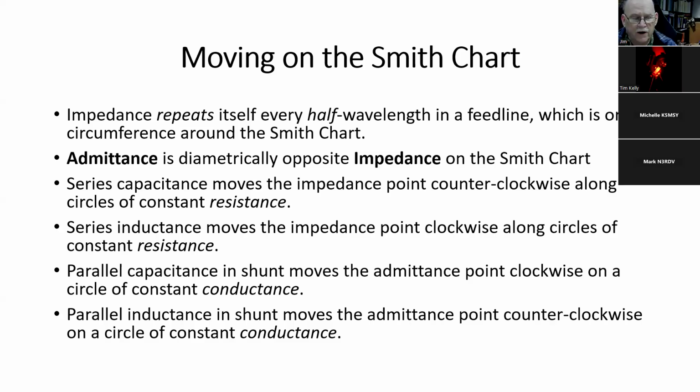Jim, yeah, go ahead. I tried to message you, but you didn't hear me or see it. On the first bullet point, impedance repeats itself every half wavelength on a feed line. Is that affected at all by the velocity factor of the feed line? Yes, it is. Good comment. I should insert into this every electrical half wavelength in a feed line. So thank you, velocity factor definitely does matter. Thank you for the question, Glenn. That was a good one.